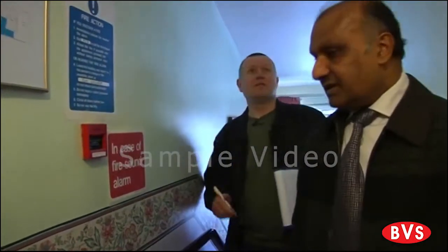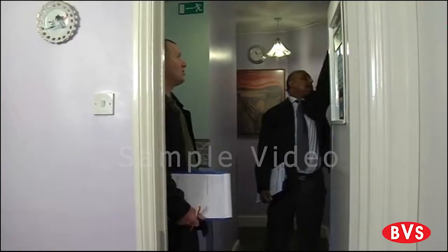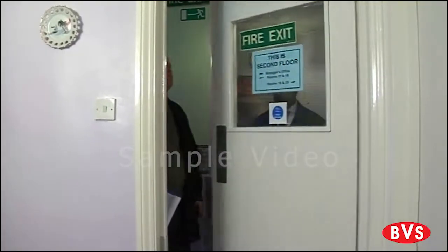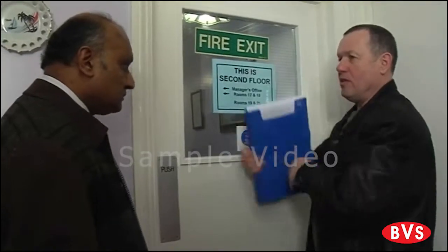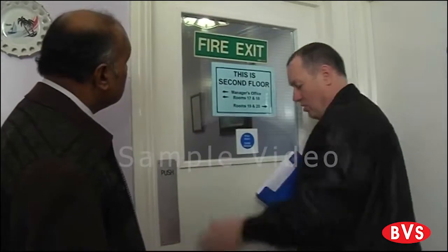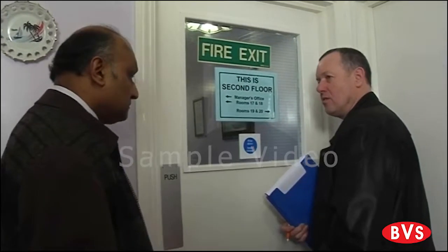This is the staircase coming to the top floor. This is the 2nd floor, and we've got only 1 staircase, as you can see. So everything on this staircase, the doors leading onto it, have to be absolutely perfect. Yes. So we need to also, once we get it to that stage, it needs maintaining. We've got a fairly straight door there. Sometimes the door can sort of warp, and you can find that it's touching at the top, but there's a gap at the bottom. So what we need to do then is obviously repair the door or the frame and get it a good fit like we've actually got there.